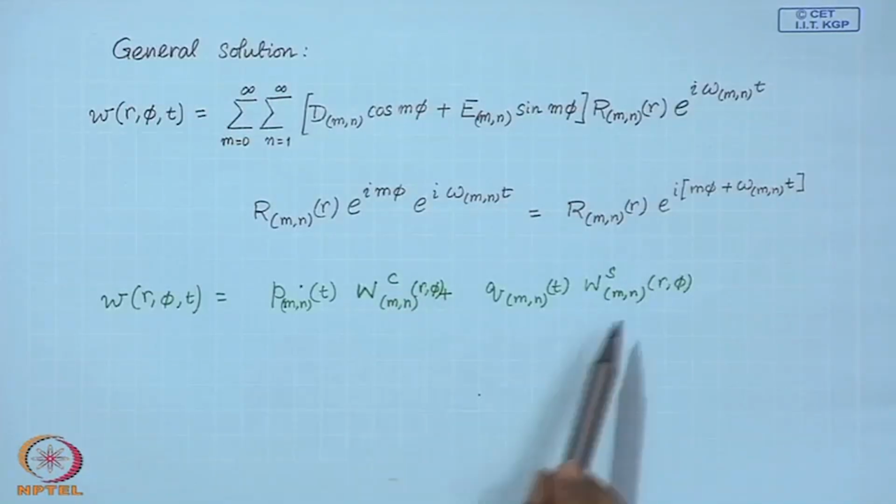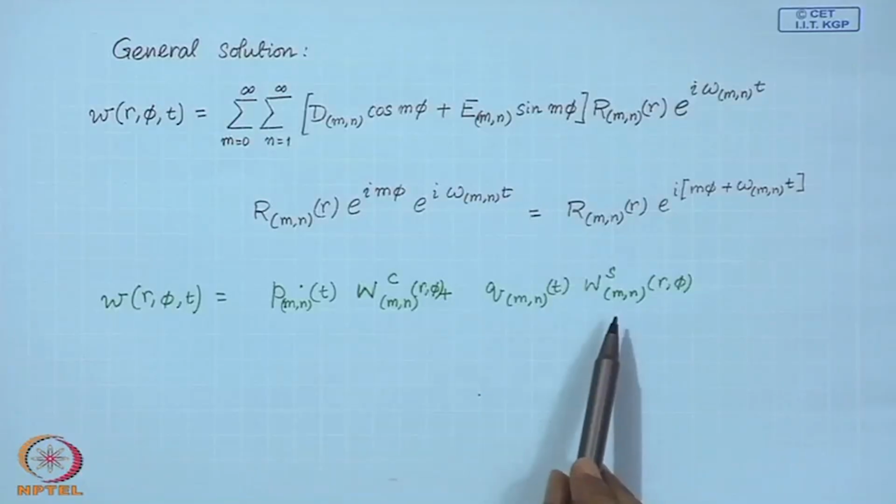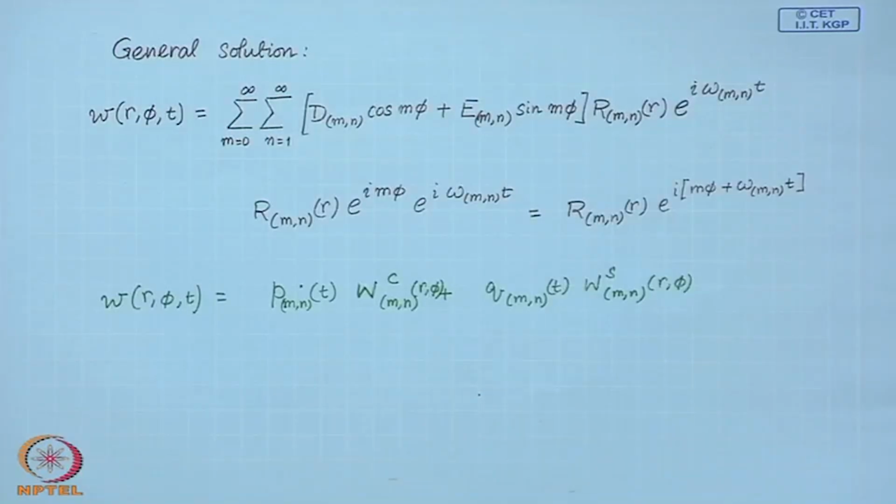Now, just as in the case of the circular membrane or membranes with modal degeneracy, we have discussed that the degenerate modes, since they have the same frequency, the nodal structure, the nodal curves in this case, the nodal diameters and the nodal circles, need not remain steady.